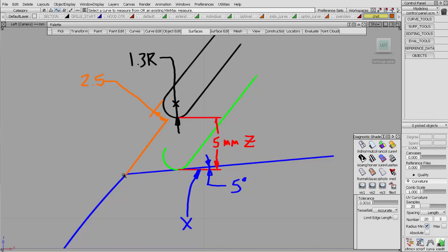Then I need to calculate in that the top of the grill isn't in X, it's up 5 degrees. So we need to find that point where the horizon plus 5 degrees, so front view plus 5 degrees, hits that. And then we need to offset the hood 2.5 to get this actual point of where this grill should be tracking this hood. Typically hoods are built to a line right here, right, for a design or a concept model.